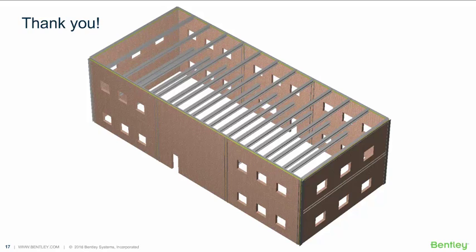Then there's a question whether the software will inform you if your shear wall design requires boundary elements, and the answer is yes. The software will let you know, and you can specify either columns or maybe walls in the other direction, like flanges. And then you can also design and assign hoops for those.